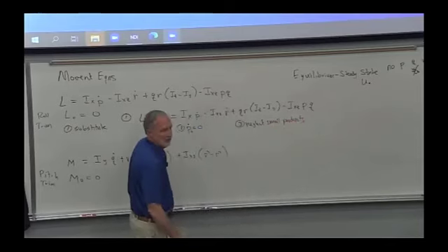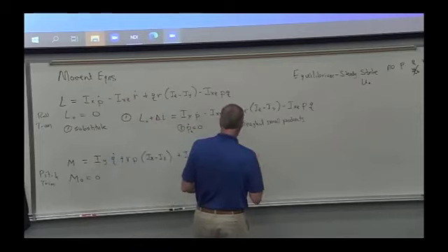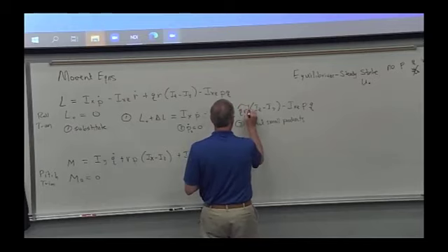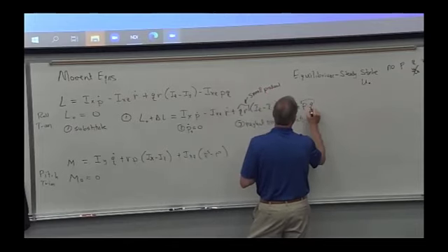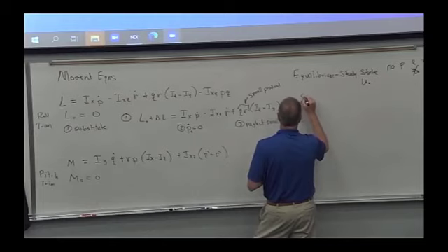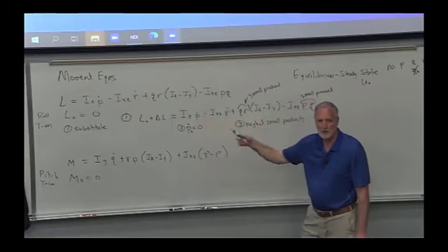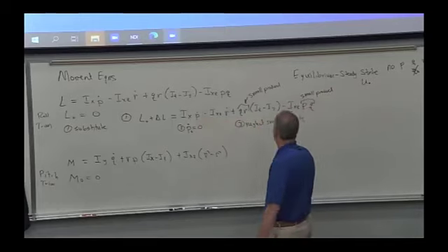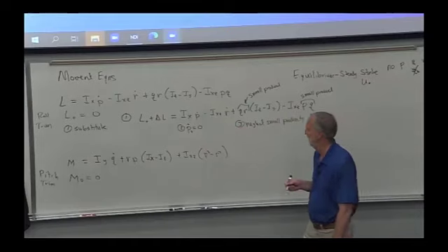products. So we look at every time there's a small perturbation multiplied by another small perturbation, and we knock that out. So we look at this, and we say this is a small product. And same thing here, we got P times Q, they're both small. So what we're really saying is this is smaller than some of the other terms that don't have products. And we don't have to deal with the sines and cosines here, so actually the moment equations are way easier because that's all you're doing.